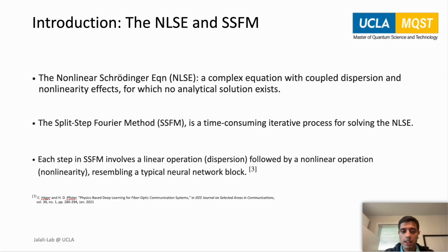Interestingly, each step in the split-step Fourier method involves a linear operation of dispersion followed by a nonlinear operation called the nonlinearity or self-phase modulation, thereby resembling a typical neural network block. In this project, I have explored the design and implementation of a neural network to approximate the solution of the NLSE more efficiently.